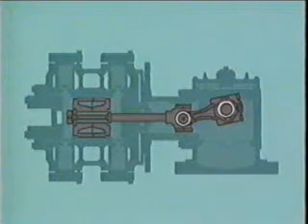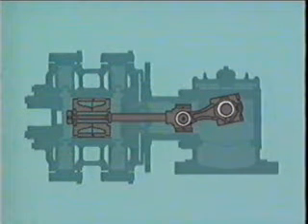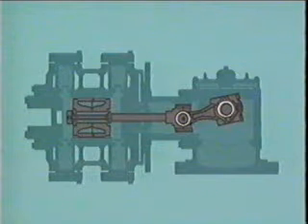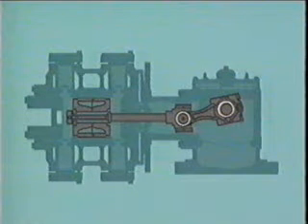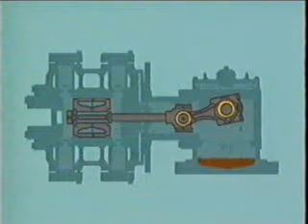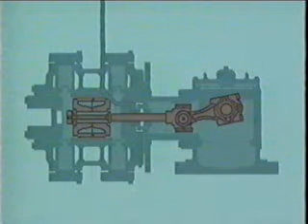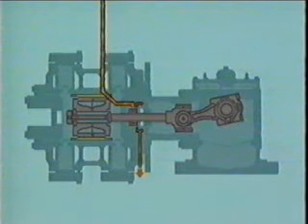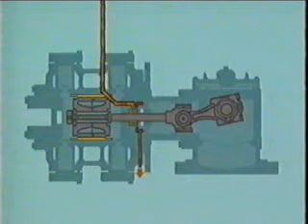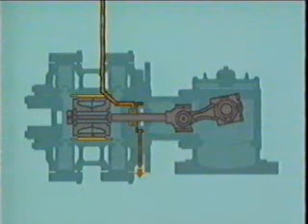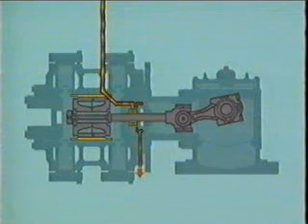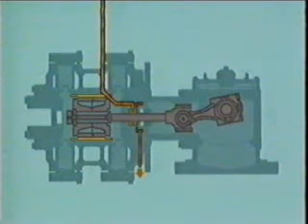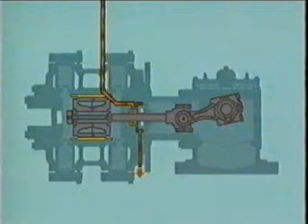Generally speaking, compressor packages have two types of lubrication systems. In one system, lubricant is pumped to the bearings and then returned to the sump. In the other, very small amounts of lubricant are force-fed to high-wear areas, like the compressor cylinders, compressor packing, and prime mover cylinders. In the force-fed system, most and sometimes all the lubricant is used up during operation.